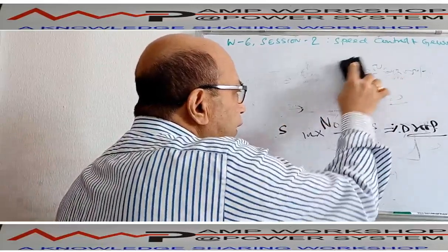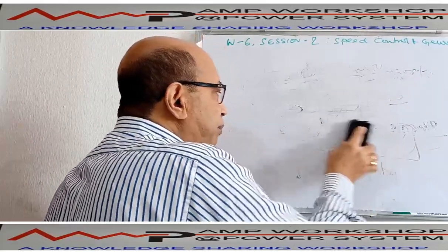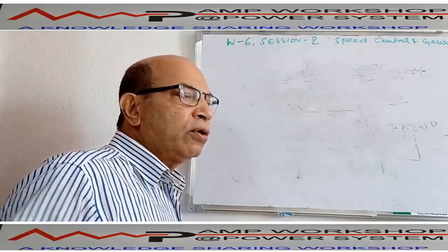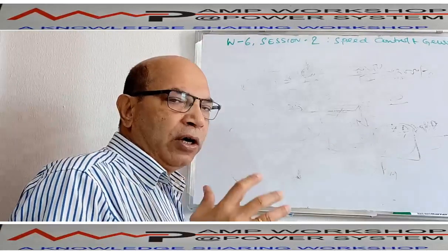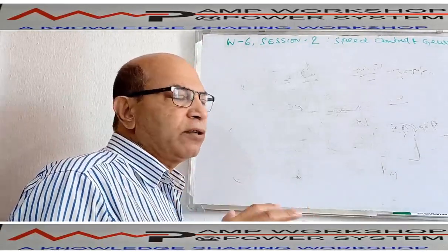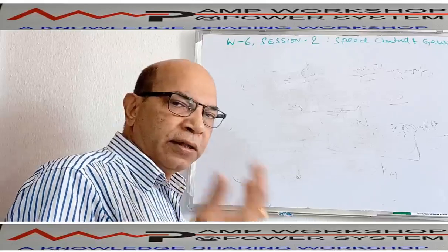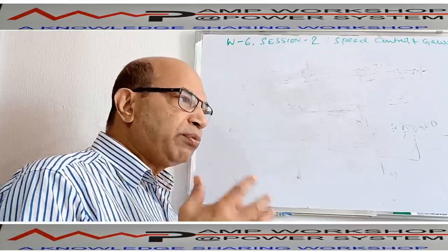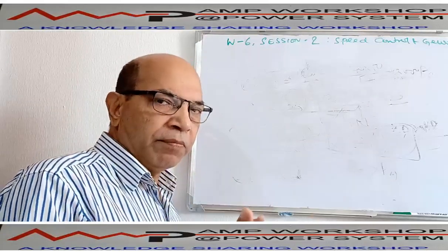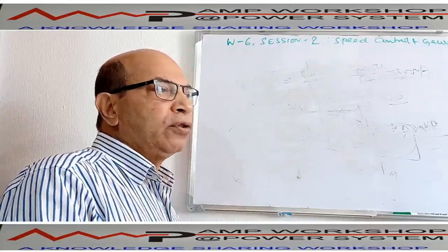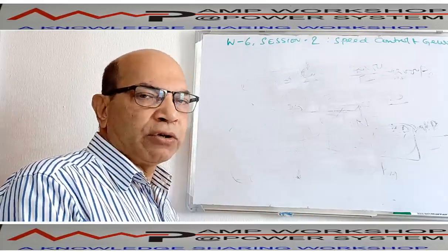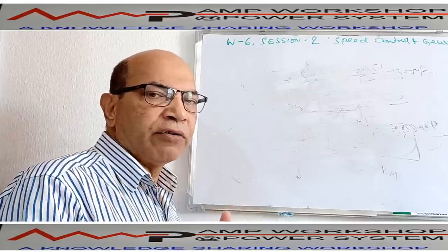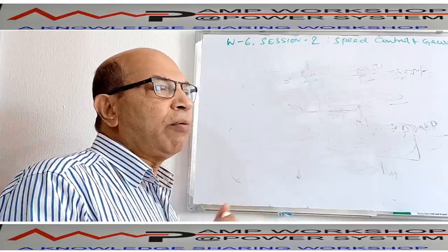Now, the moment the speed drops or picks up due to putting on more electrical load or withdrawing electrical load, our intention is that the frequency should not change from 50 hertz or 60 hertz to another value. We have to maintain the frequency. So how will we do this? We maintain this frequency through equipment called a speed controller or frequency controller. That device we call the governor.